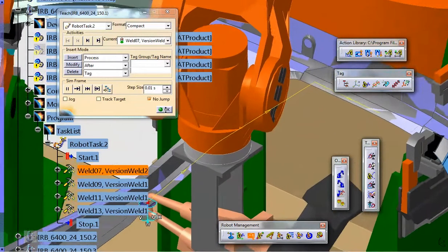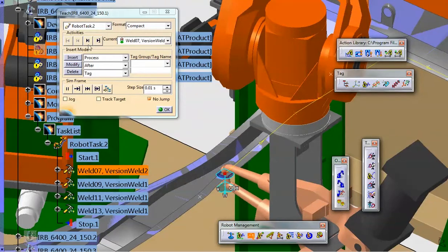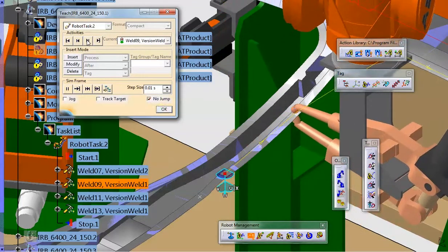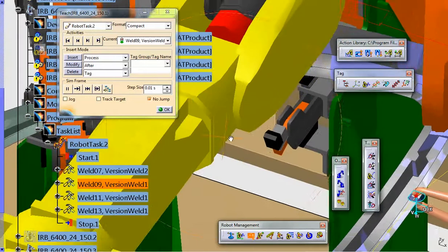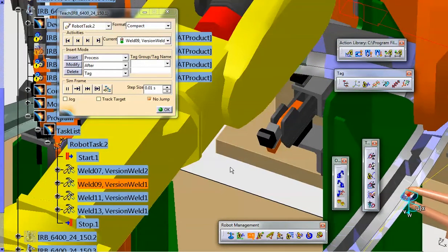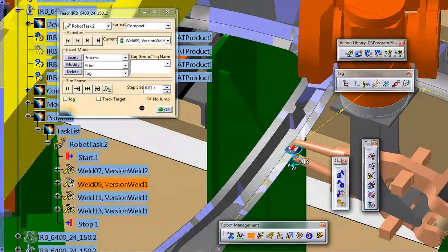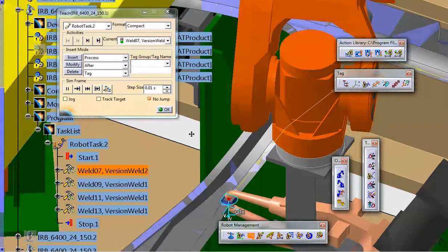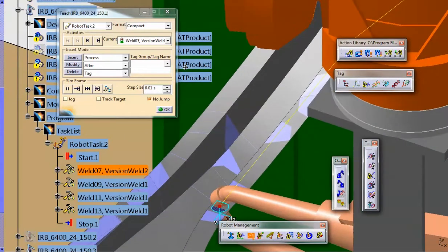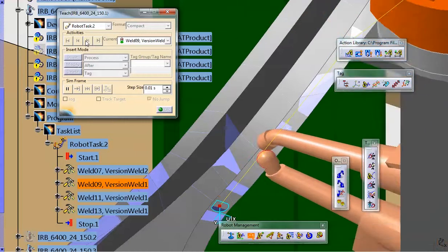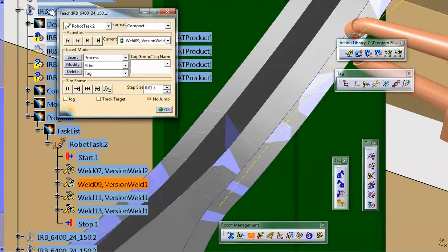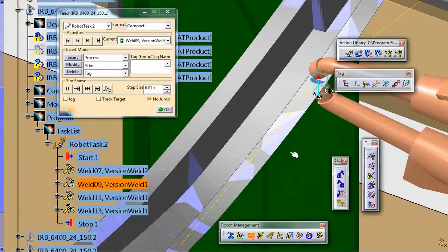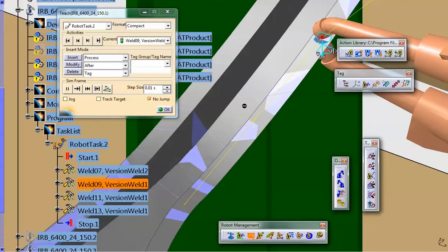So let's zoom in now on those first 2 welds. And I've got collision detection turned on now. And so you'll see a little red mark. You have to look very closely, a little red mark where the lower anvil of the weld gun appears to protrude through the part itself. You see that as a little annulus, a thin red annulus. Now, one mode of running the collision detection is to actually stop the program when a collision is observed. But in these early stages of design, the program would be stopping all the time. So we're just going to allow the graphics to show us with colour when there's a problem.